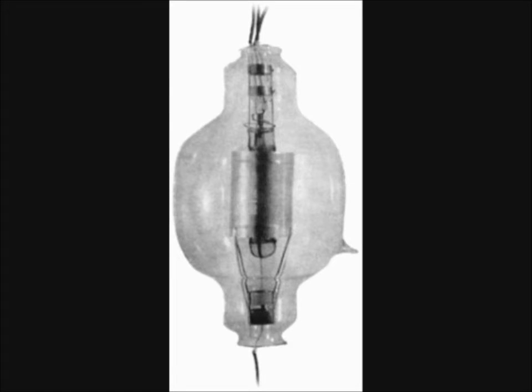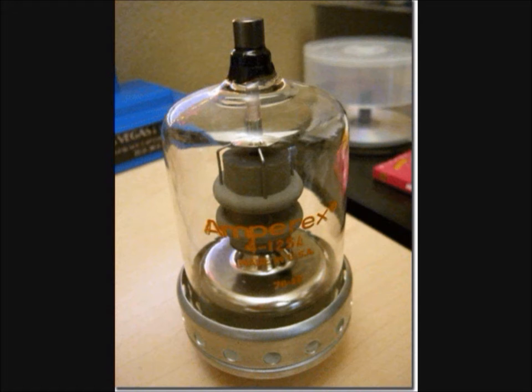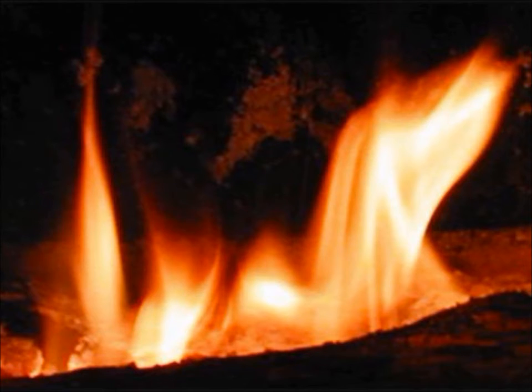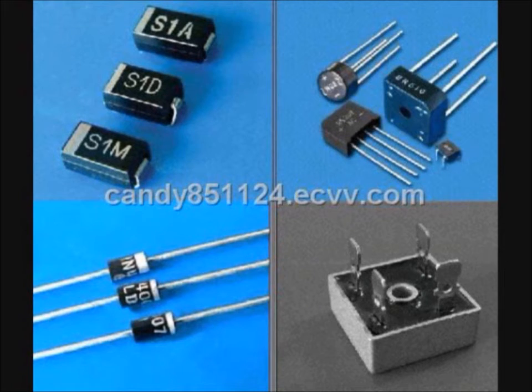Thermionic devices were not only more fragile than solid-state devices, they produced much more heat, had a shorter lifespan as they reacted with the gas in the tube during emission or just melted, had slower switching speeds, required very high voltages compared to solid-state devices to bias things to correctly rectify signals, and would not work once air was let into the vacuum tube. They also required a separate heating circuit and were overall less energy efficient than semiconductor devices. With all their disadvantages, it is hence unsurprising that thermionic devices were replaced by solid-state devices.